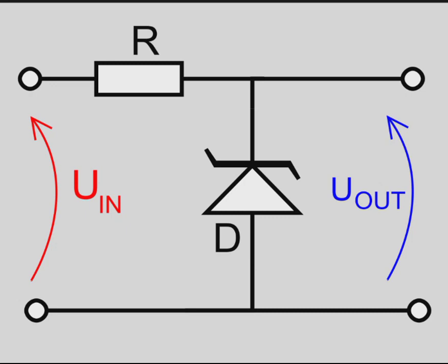Okay, so this property of a Zener is used to maintain the constant voltage across the output terminal. When it conducts the current, it holds the Zener voltage across its output terminal. So even though there are variations in the input side, the diode enters into breakdown mode and it will maintain that voltage across its terminal.